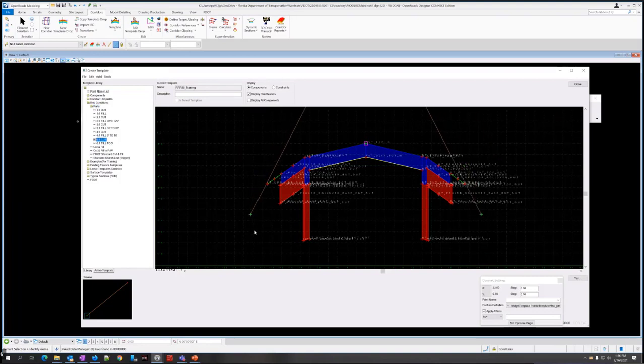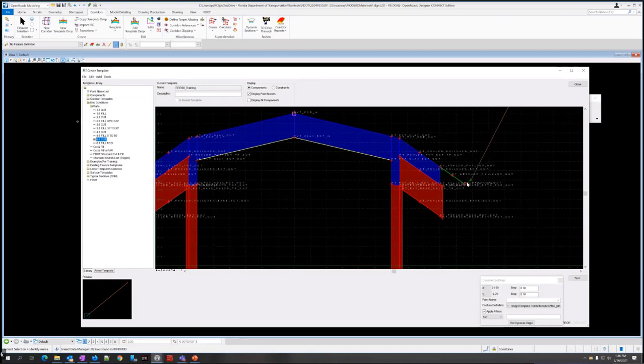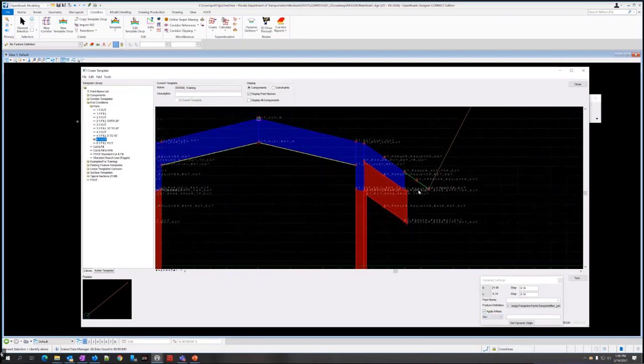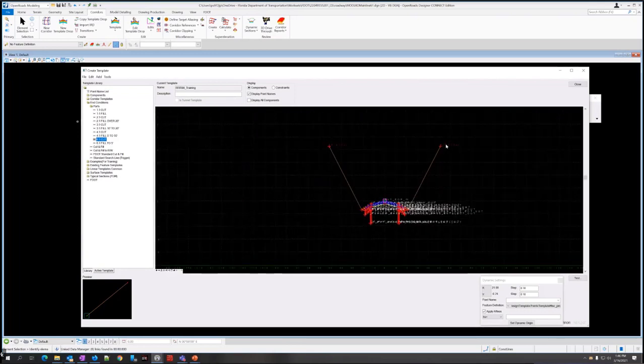So if I drag it in here, over to the right side, mirror is still selected. All right, right click before and selected it. It's still selected. And if you uncheck it, you can just go check it back. So just snap it over here to this outside point, which is the right UP shoulder underscore out. Make sure apply fixes is still turned on. We want those on. So it'll name it here.